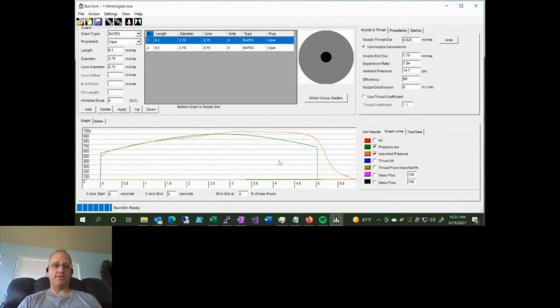Like I said, ideally, I'd like to be able to simulate it, but I haven't got to the point yet where I can reliably characterize a propellant for its erosivity and then define that in a way that you could plug in here and say, okay, given an erosivity factor of X that starts at mass flux Y, and have it start simulating additional burn rate based on that. I've been thinking of ways to do it, kicking it around, haven't done it myself. There's a lot of papers out there and a lot of research on erosivity and how to predict it, how to calculate it, that kind of thing. So a lot of interesting reading on that as well.